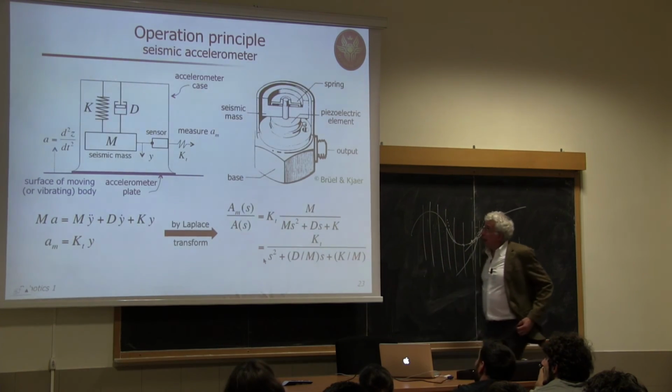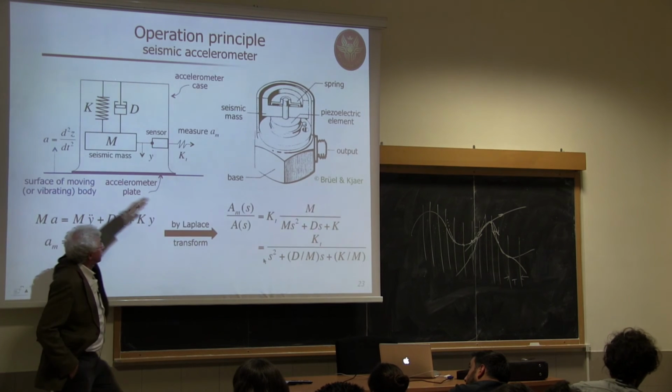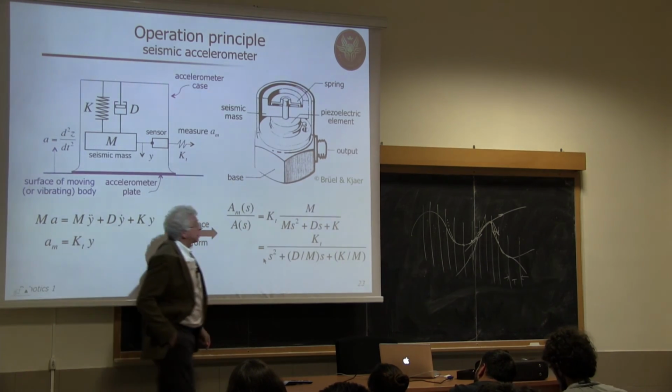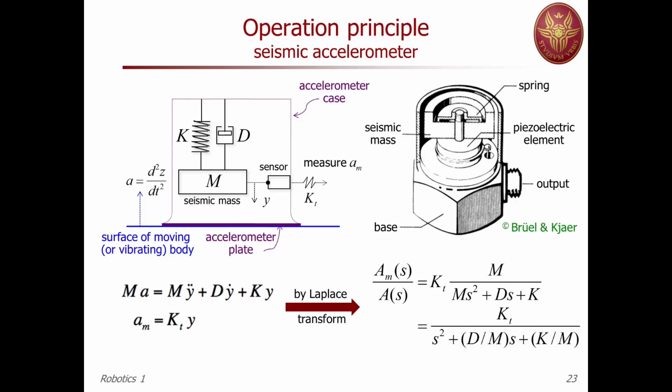Even if you have an integrated solid-state implementation, the principle of these devices is very similar to this traditional so-called seismic accelerometer. So let's study a bit the behavior of this. This is the box of your accelerometer, and this is how it would look with a section that shows the single components inside. Inside, you have a suspended mass of known value, of course.